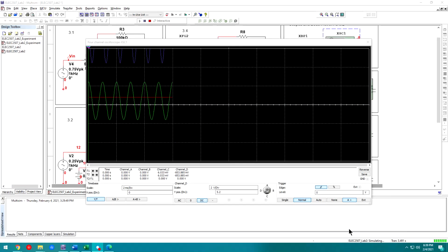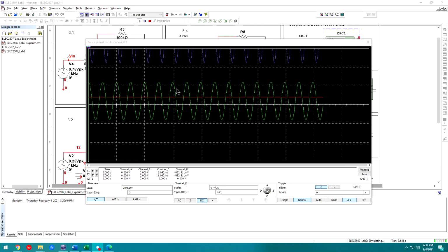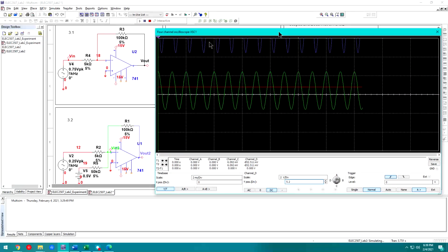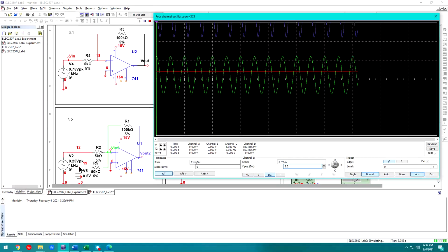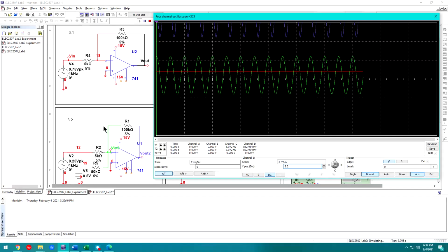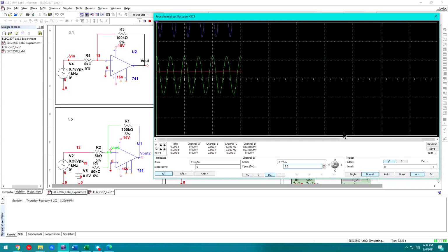So when you first open up the scope, you'll see that the purple waveform looks like it's way out of bounds here, right? And that's because the channel's DC coupled, right? And you have a DC input coming in here, and it is also getting amplified, right?